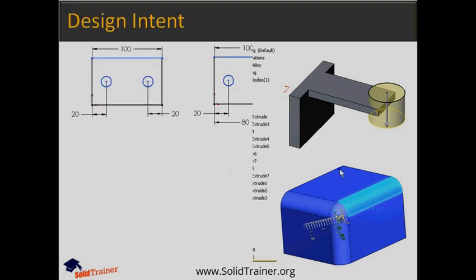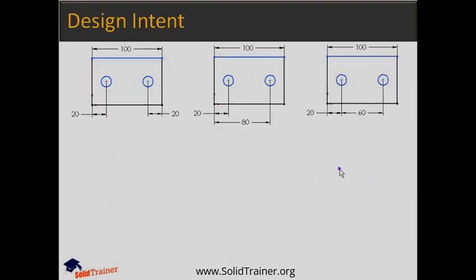In order to use a parametric modeler like SolidWorks efficiently, you must consider the design intent before modeling. Design intent, or your intention for design, is one of the most important factors often ignored in design practice. While learning the software or following our daily routine of modeling practice, we tend to concentrate more on the commands rather than our intention of creating the basic design.